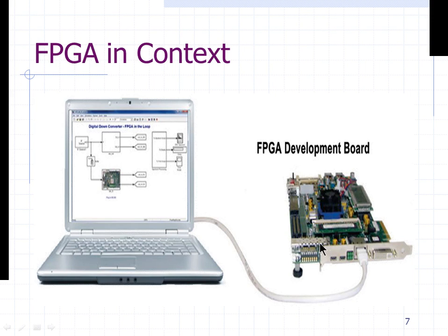Nowadays, you get a lot of different FPGA kits which you can buy directly from the market. They will have this simple USB interface where it will be connected to the PC. You can program the FPGA chip through this interface, or you can debug the FPGA chip using this interface.